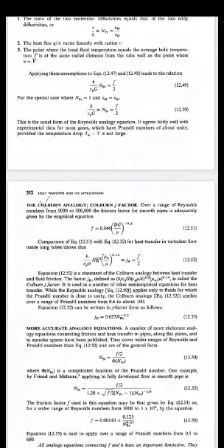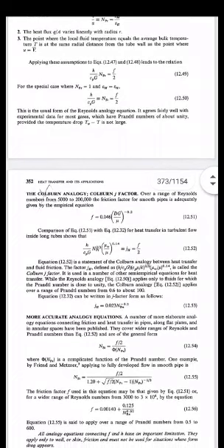Now if we compare these equations, then easily we can find the j factor: h upon Cp G into the Prandtl number to the power 2 upon 3 into the ratio of mu w upon mu, that is the viscosity correction factor, is equal to jH is equal to f upon 2. This equation is the statement of the Colburn analogy, which gives the relationship between heat transfer and fluid friction.